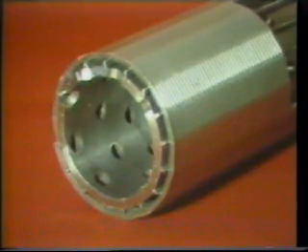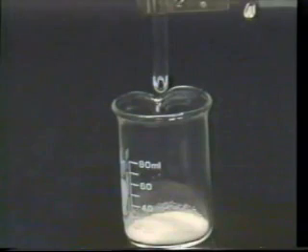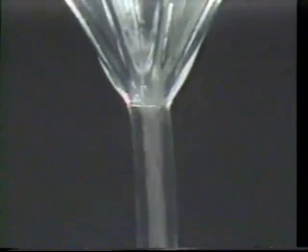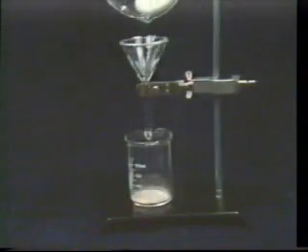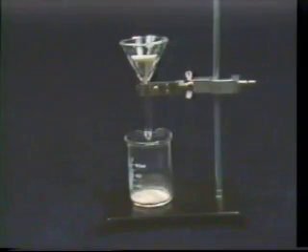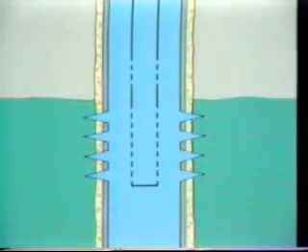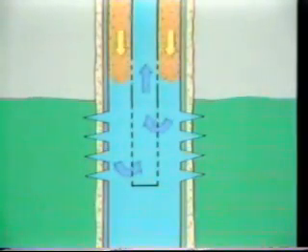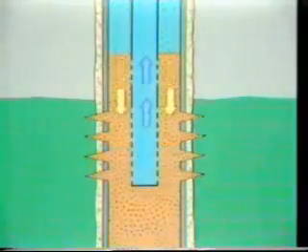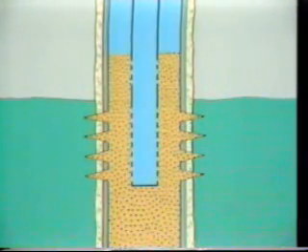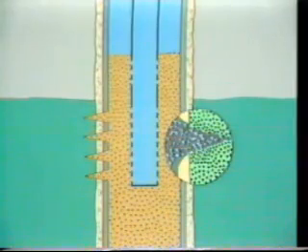Metal screens or gravel packs work in a manner analogous to a large crowd of people trying to leave a theater through a small door. Each could pass through individually, but when several try at once, they form a bridge, preventing those at the rear from moving at all. In sand control, bridging methods employ wire-wrapped screens with openings carefully sized to allow the formation sand or gravel pack sand to be deposited against them. Gravel packs are designed based on the analysis of the formation sand grain size distribution, so that the screen and gravel pack sand will prevent formation sand movement, but not inhibit formation fluid flow.